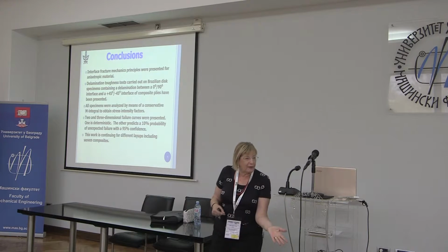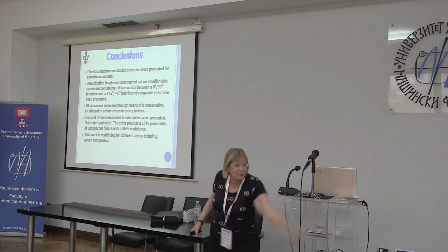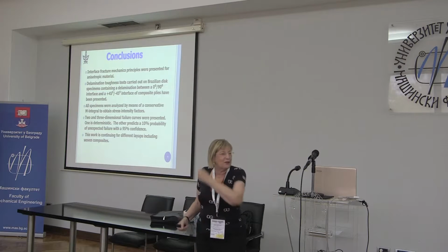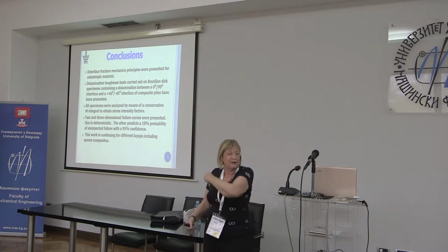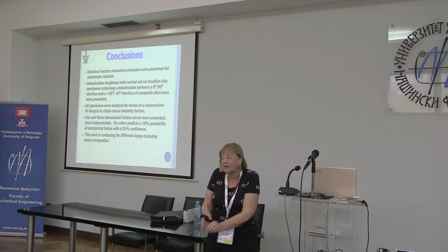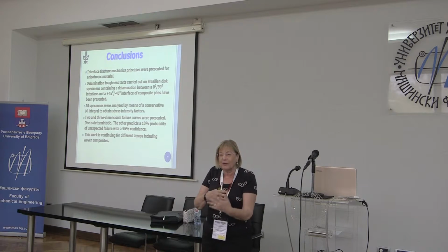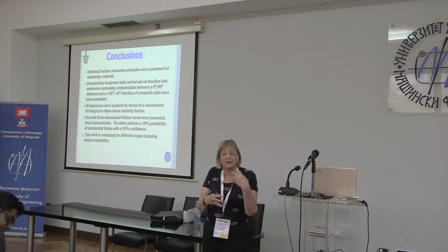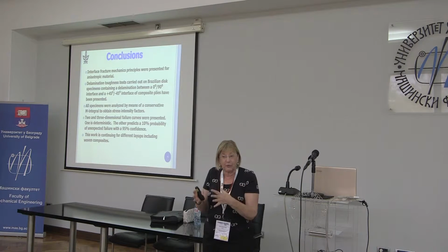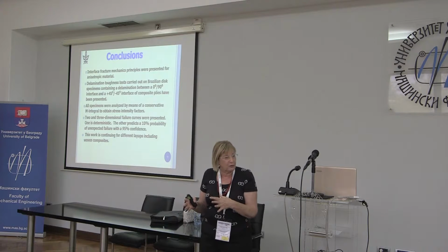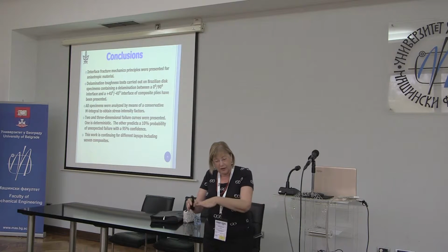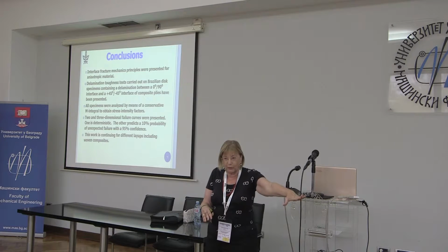So he had a fight with his wife, so he's just throwing down that epoxy, or he's in a very good mood and he's singing and he's putting down the epoxy, or he's putting very little epoxy. There's lots of voids in the material, and it's just not made like a prepreg, but a prepreg is much more expensive. And so she has plus 45, minus 45, and then she has 0 degree direction.